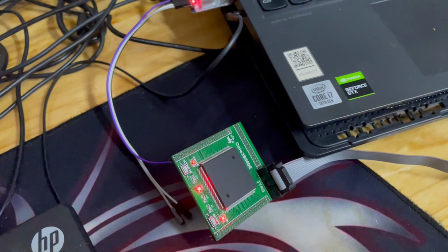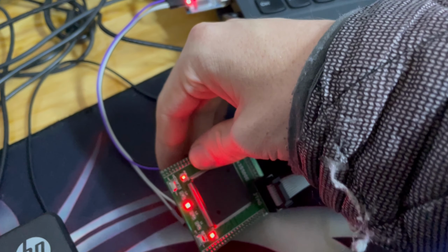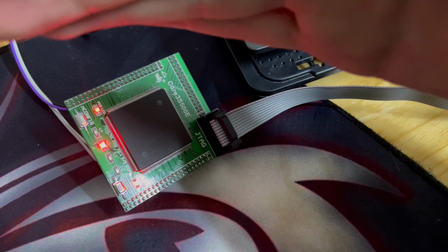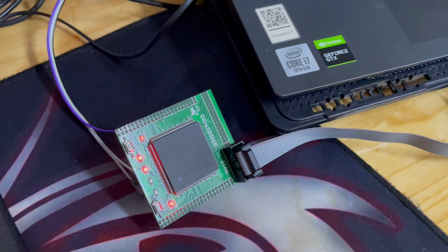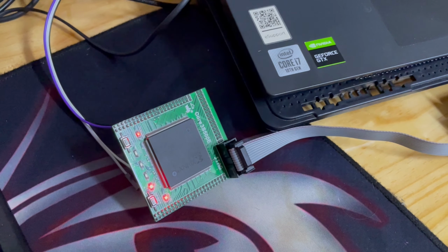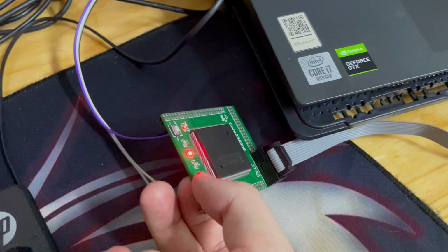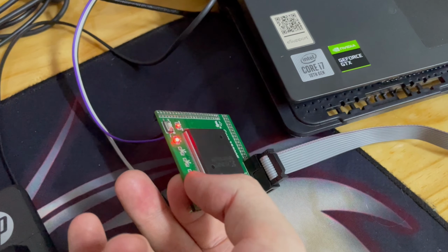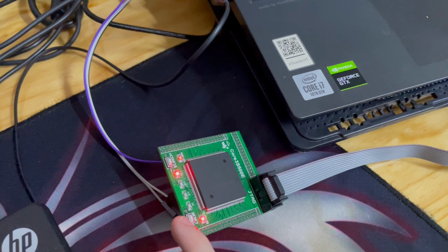But before I talk about that, let's first see what happens when we power this down and back up again. So there you can see I just reset the power. And now it's running the demo program that came with the chip. It's like it lost the configuration that we just programmed onto it. So let me go ahead and reprogram it. So I'm going to hit program. There we go. So here's our Logisim circuit running on it. But it doesn't work as intended, as you can see. It behaves a little erratically. And the reason why that happens is because of bouncing on the reset button.